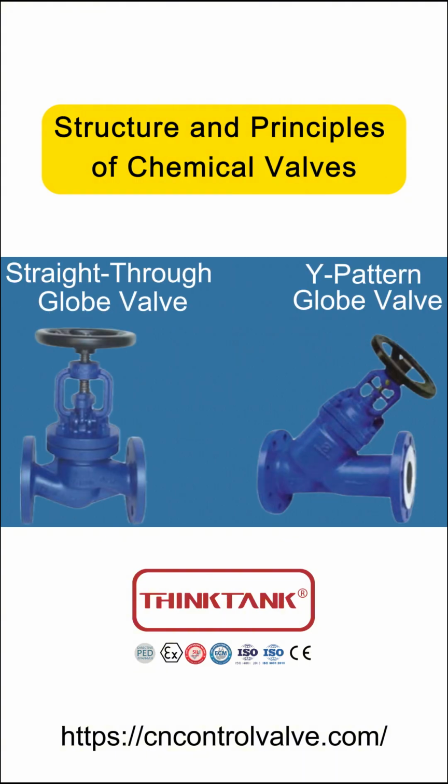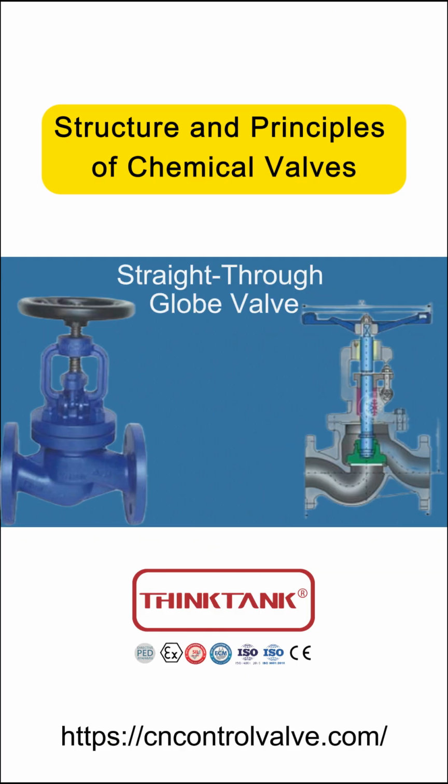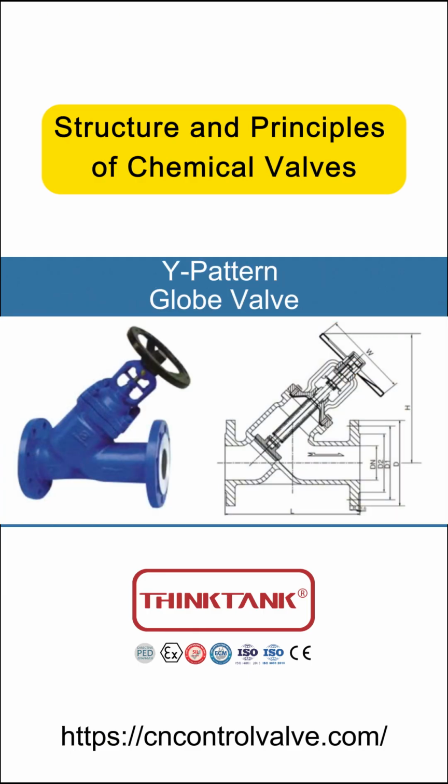Common types of globe valves include the straight-through type and the Y-pattern type. Their main difference is the flow path of the media inside the valve. The Y-pattern type causes a slightly smaller pressure loss. The straight-through type is the most common model. Its internal structure is similar to a Z-shape. In use, they can provide some flow regulation. Compared to ball valves and gate valves, there is less wear on the sealing surface during regulation, making it suitable for small diameter pipes. The Y-pattern type has less impact on the media's flow direction. It is generally used in situations where there are requirements for media pressure loss.